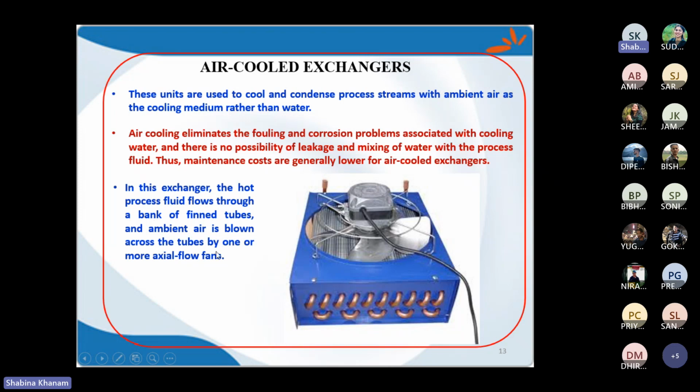What is my system? My system is this, where I have the tube banks as well as the fins. When this fan is placed at the top, it throws air over this tube. It means it gives positive pressure in this system. Therefore it is called forced draft.